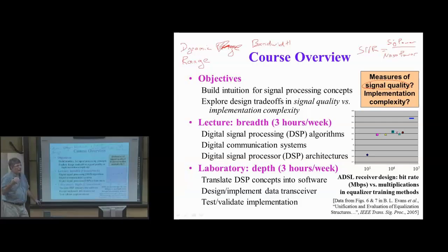So in audio, we don't hear all frequencies. Normal hearing is roughly 20 hertz to 20 kilohertz. The SNR that we care about is in that range. We don't really care about it outside of that range. And furthermore, our auditory system is not a flat response over frequency. It has a shape to it. Okay, and we have a peak around 1 kilohertz in our hearing in the low-level processing of our auditory system.